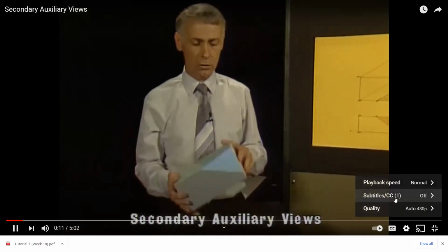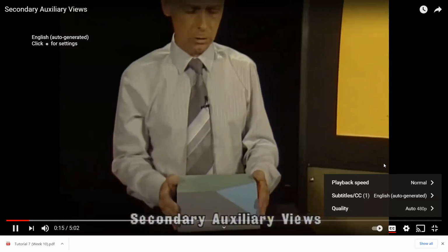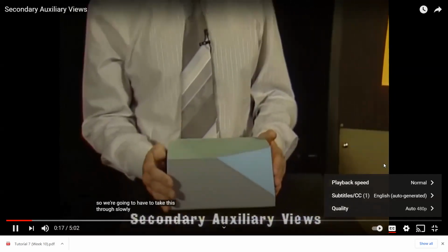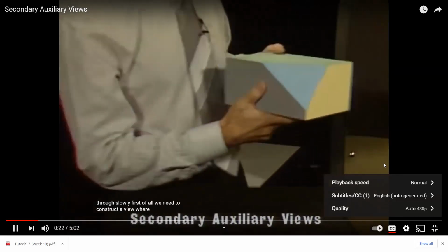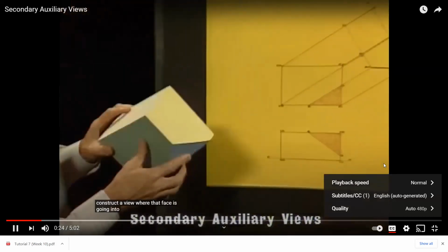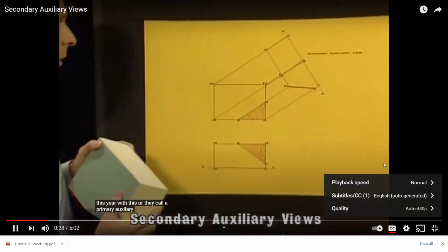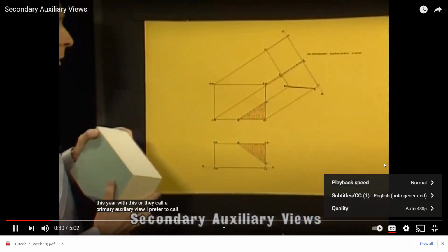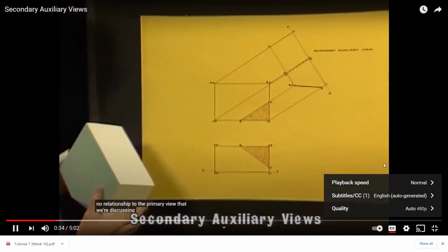To see the true shape of that face. Concept, so we're going to have to take this through slowly. First of all, we need to construct a view where that face is seen in true shape, done it here with this, what they call a primary auxiliary view. I'd prefer to call it an intermediate view because it has no relationship to the primary views that we were discussing before.